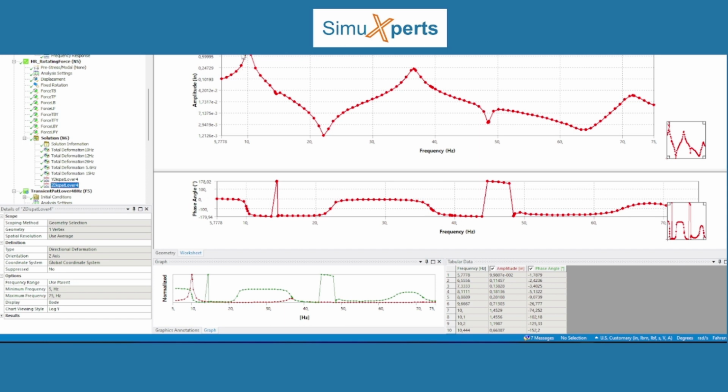As I mentioned before, it's a lightly damped system, so there is a lot of amplification around the resonant frequencies. Here is the first natural frequency around the weak axis at 10 Hertz. Here is number 3, around 36 Hertz. As we saw before, there is a significant response at these frequencies.